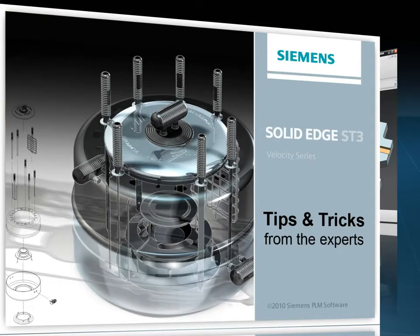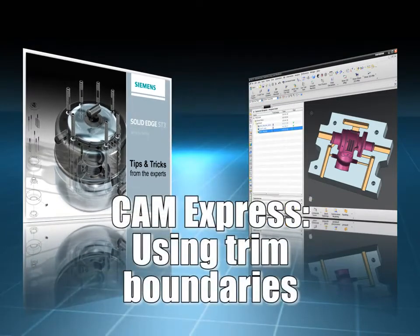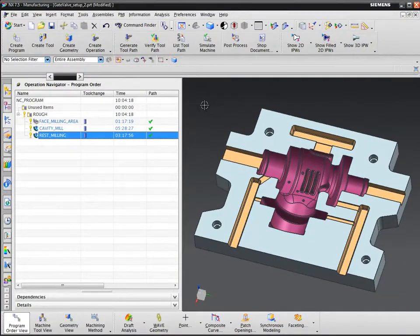Face selection is a great way to save time and maintain associativity generating toolpaths, but sometimes using boundaries may be a better solution. Boundaries can be used to stop cutting in areas you don't want cutting to take place. Creating boundaries in CamExpress is simple and doesn't require you to chain the boundary elements, so elements selected don't have to touch each other. In this example, Jim Wright will show you how to create boundaries and when it's a better approach for defining a toolpath.